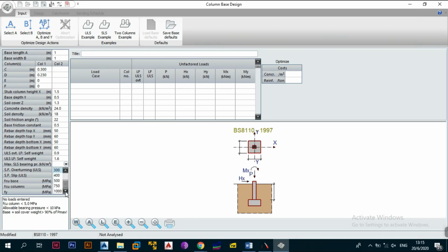But the best thing is that is why they tell you to go and do an actual soil report, so that you may try and have your foundations at a depth that allows say 500, 750 or 1000, because once you get a bearing pressure of about 1000, this means the area of your foundation will greatly reduce and you save cost of the concrete. All you'll just be doing is having people excavate to a deeper foundation, and this just means more money for labor as opposed to for steel and concrete. But remember, steel and concrete always cost more than your labor. So in this case, since the average is usually 250 or below 100, we're just going to be putting 250. This is for loose sand, which is low bearing pressure, and the K modulus of about 4.8.